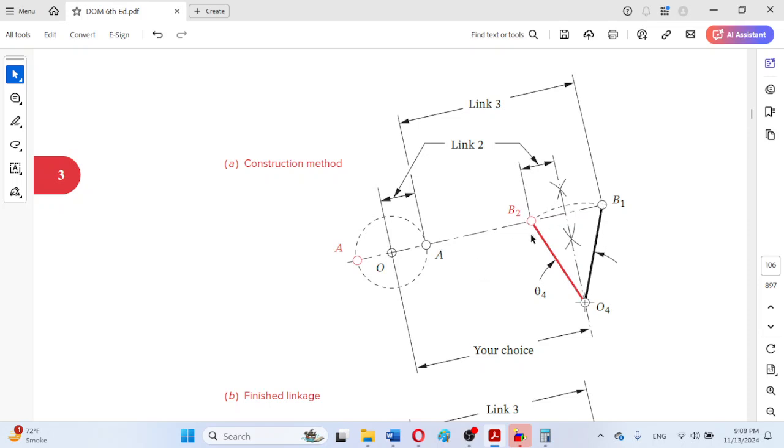That is the reason. If we want to design the quick return, which I will cover later in the video, the crank grounded revolute will not be located on the line connecting the extremities of this rocker link. It will be offset from this line, either in this direction or in this direction. That is the principle.